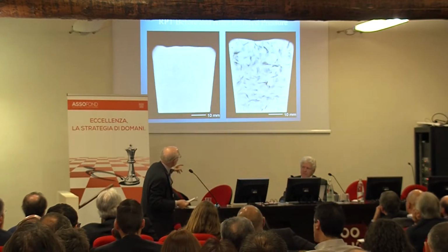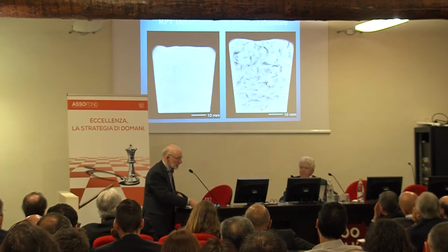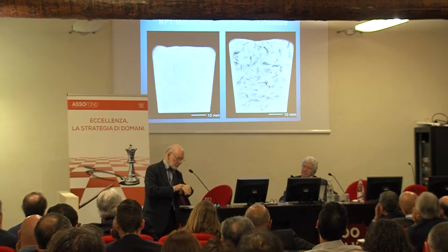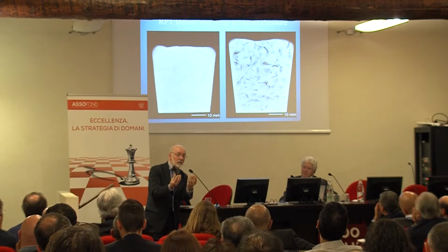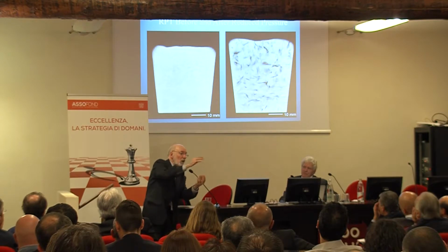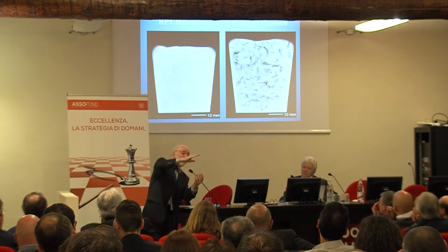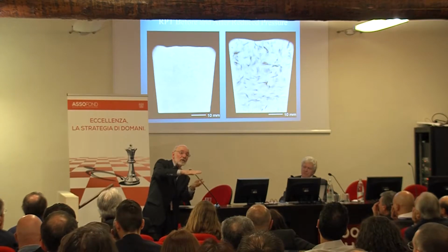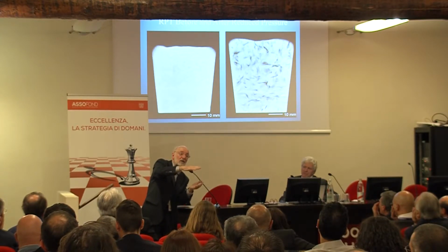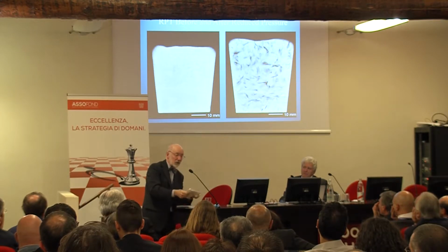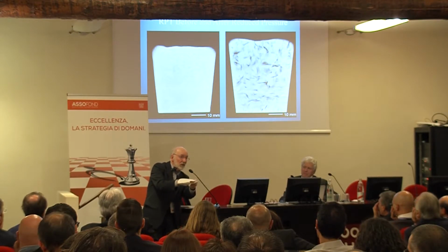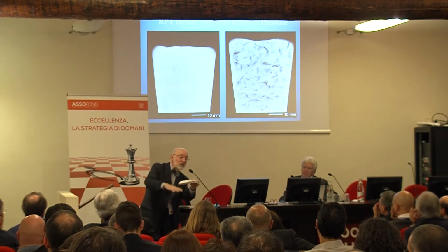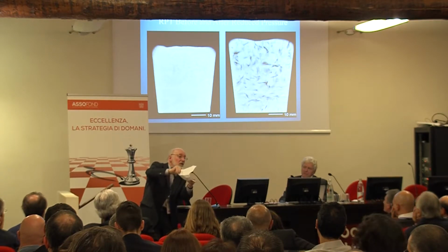Okay. And this is an interesting instance of two small molds in which we took aluminium and poured it into the two quickly, and then on one of them we put a jar over the top, pumped down the vacuum to about 1/10 of an atmosphere. What I hoped would happen would be that the small amount of air between the bifilms, because we're at 1/10 of an atmosphere, would grow by 10 times.